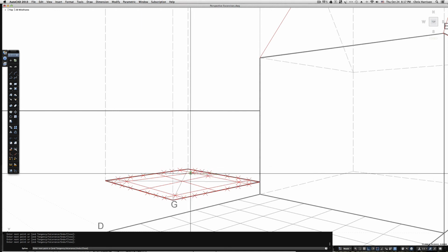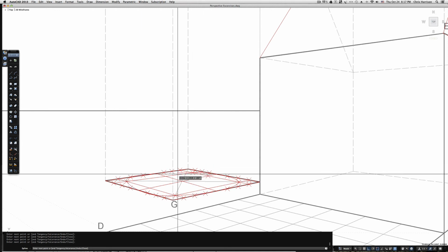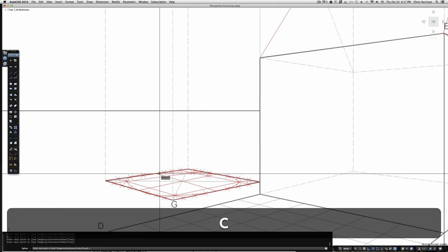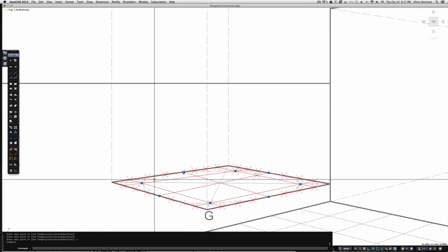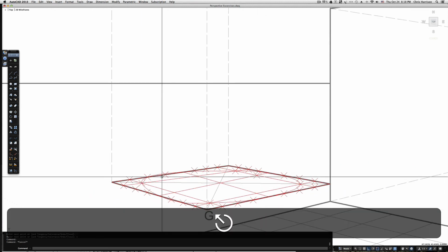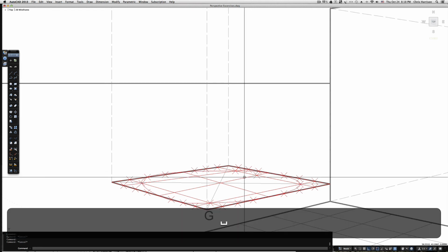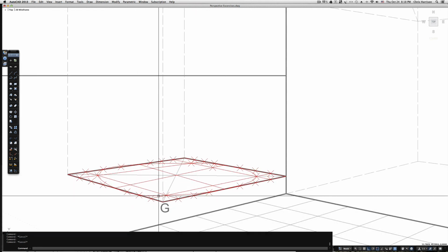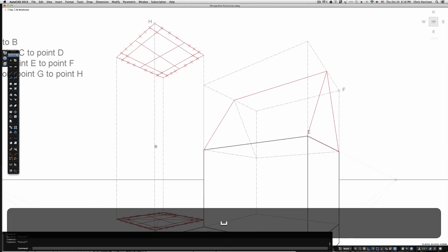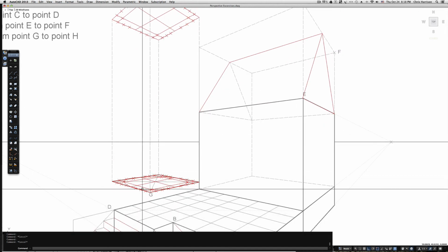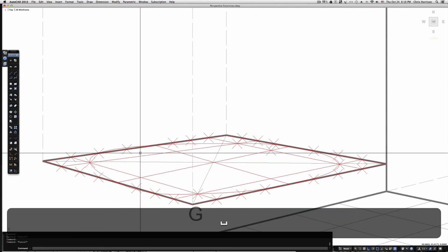And I'm trying to see my arc. We're just going to close that. Alright, in doing this I'm going to have some overlap here, and that's just the cleanest that I know how to do in AutoCAD. So it's easier to do this by hand for this case, but we can still clean this up to get the primary shape. As you can see, it's just following those points around, but it should be completely tangent to it and shouldn't overlap when you draw it.